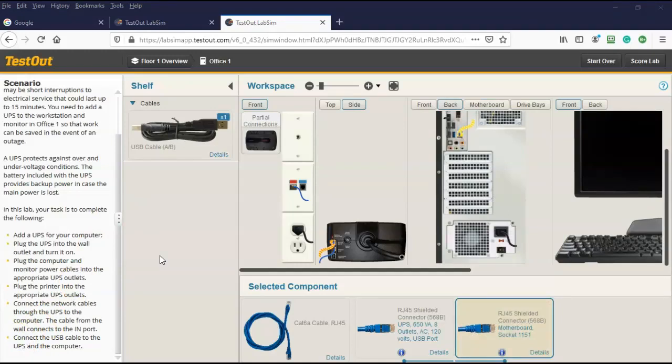Another feature of a UPS is that it comes with software that can monitor your computer. And you can say in the configuration of that software that in the event that my computer loses power, I want you to gracefully shut down my machine. And the software should do it. That's in case you're not available to gracefully shut down the machine manually. But for this to happen, there has to be a connection between the UPS and the computer. Let's see how we do that.